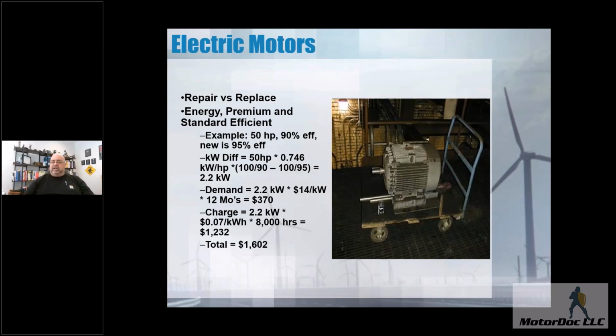Used to be a trick we did for a repair shop I was involved in. You'd go in, the exact same load, exact same settings on a 100 horsepower motor. You knew that the core losses increased by clamping on and seeing several amps increase in current draw, not energy consumption. The kVA went up. If I took a kilowatt meter, I would see a slight increase in the kilowatts.